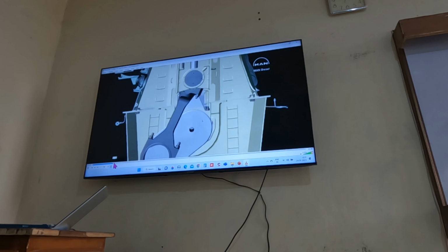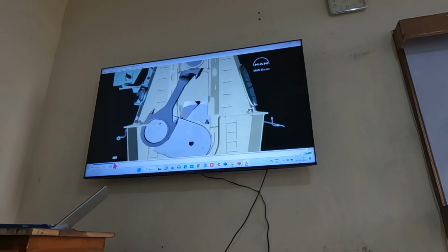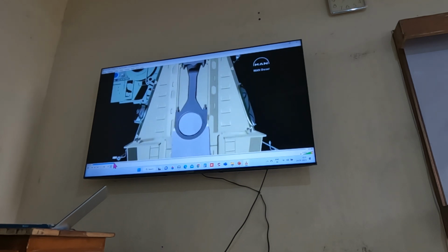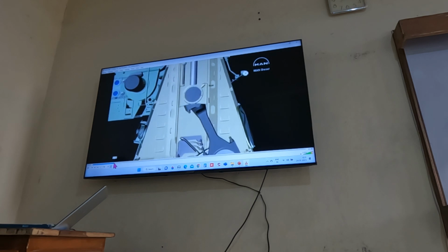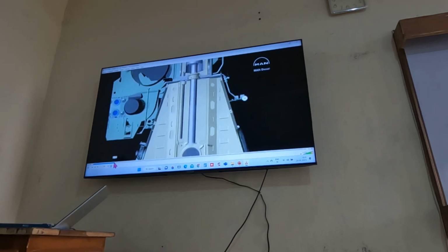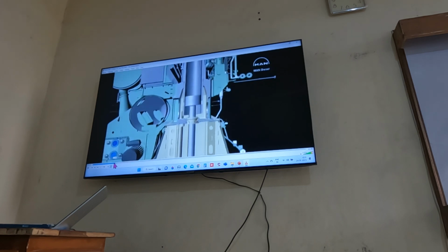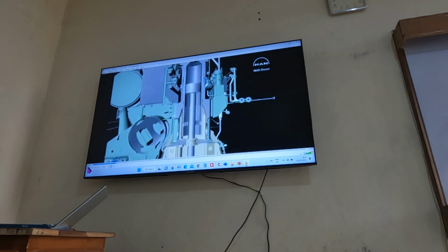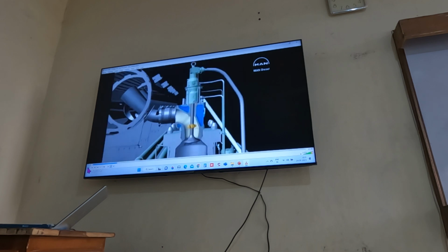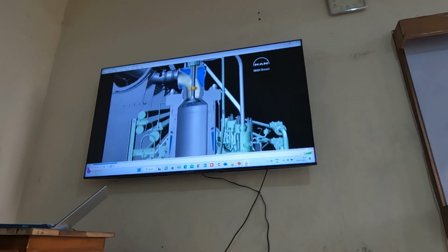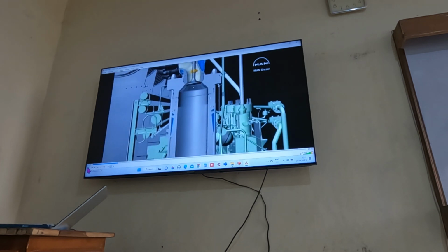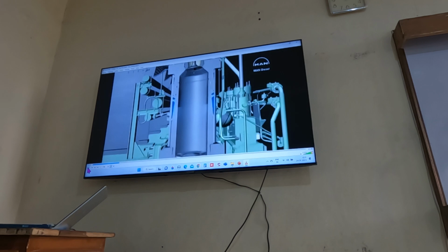This sectional view shows the functions which the most important parts of the engine have to perform. In the upper part of the cylinder, an amount of fuel oil is burned, which causes the temperature and thus the pressure to rise in the combustion space.